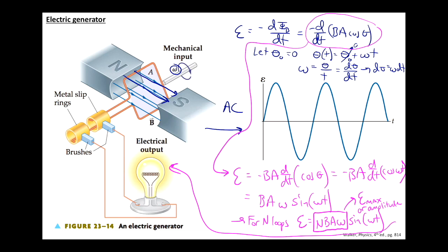So if that happens, we're going to generate, from Lenz's law, a clockwise current. Okay? Everybody all right with that? So we're going to start here with current that is clockwise, and that is the induced current because I'm mechanically spinning it, for the exact same reasons why we had back EMF before. Once we do that, take a look at, let's say, the wire right there at the top next to the North Pole where I drew the current.